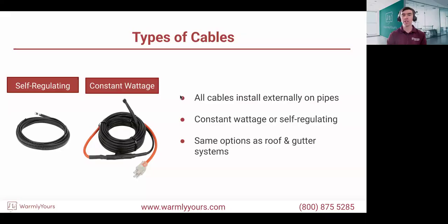It looks like Ryan is, correct me if I'm wrong, trying to clarify if the snow retention should be installed before or after a heating cable. I think the answer here is pretty simple. Yes, you definitely want your snow retention system to be fully installed and done before the cable installation, because first of all, that's safer.